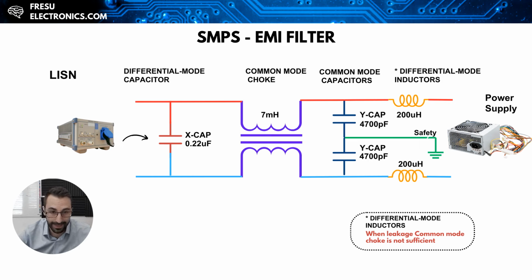The values and the characteristics of the capacitors used in these filters are regulated by the safety agencies. For example, for line-to-earth connection, a special capacitor called the Y capacitor is used, which is listed and also approved by safety agencies such as Underwriters Laboratories, or UL, and its value is also limited to limit the leakage current, since leakage current is considered a shock hazard and is also regulated.